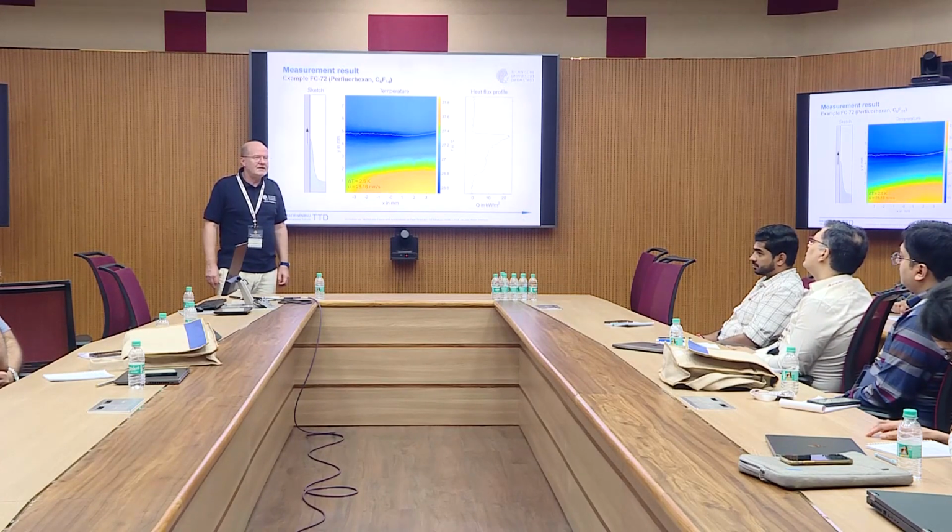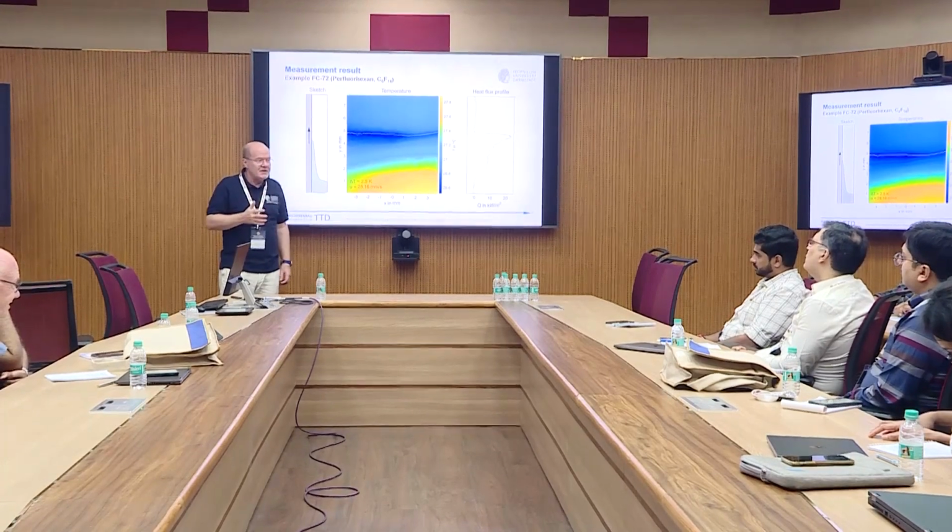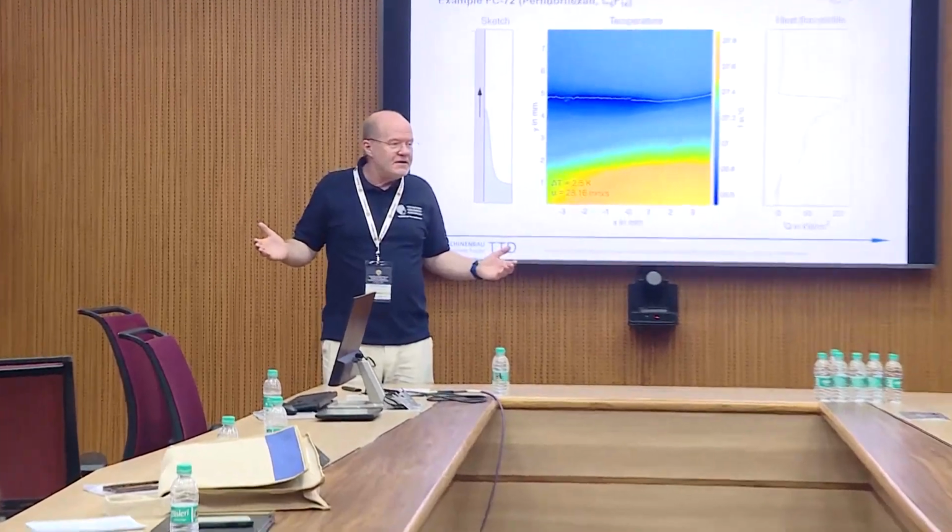Of course, we are not able to, and that's why we built this controlled experiment where we can really set the velocity. In a real boiling experiment, the velocity is first of all changing from 0 to plus 3 millimeters per second, to minus 3 millimeters per second, and this is fluctuating. So you have all the different velocities in a boiling situation, but you can design the surface in such a way that, at least for the growing bubble situation, you have the microlayer formation.